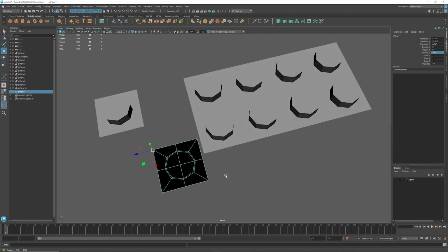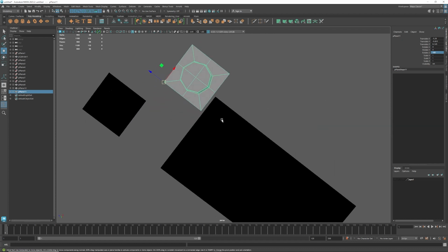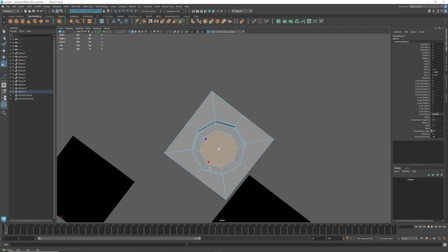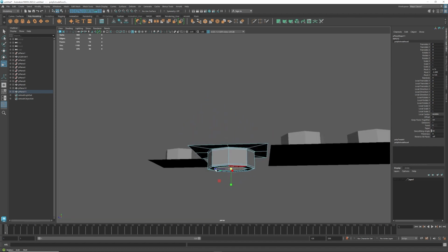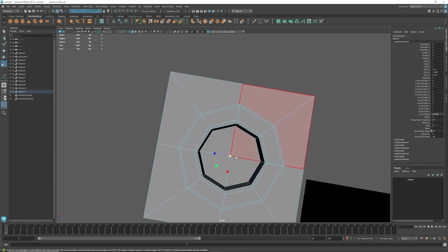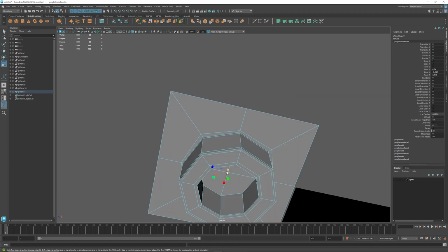And then we are going to edge loop here. So I'm going to do a couple different things. The first thing I'm going to do is go to face, grab these 4 faces, and shift extrude, and that's going to scale that inward like that. Then I'm going to shift extrude again a little bit more, and extrude it up just a hair, and then extrude it up quite a bit, and extrude it again up a little bit more. Then I'm going to grab those, shift extrude, and scale it inward just a hair.